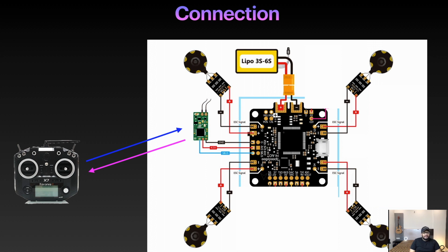Now it is the duty of the flight controller to do the function that the drone operator wants it to execute. And how is it happening? It will do all the maths. It has the firmware which is responsible for doing all the maths. After doing all the maths, the flight controller will send a signal to each and every ESC, and tell them what RPM they should be rotating at that particular instant. So exactly as I mentioned in this flow chart, the drone operator is sending the values of roll, pitch, yaw, and throttle to the receiver. The receiver passes that to the flight controller. The flight controller computes the current RPM of each motor and passes it to the ESC.